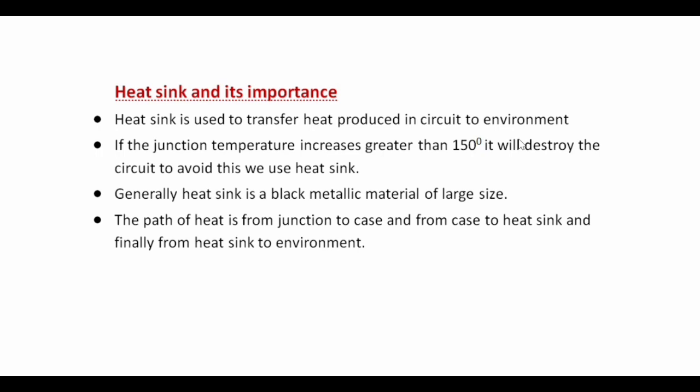If the heat is there, then the temperature increases. If the temperature increases, then the collector leakage current increases, which will damage the circuit by going through thermal runaway. If thermal runaway occurs, then the complete circuit will get exhausted, and to checkmate this, we require a heat absorbing device. What is that heat absorbing device? It is the heat sink.